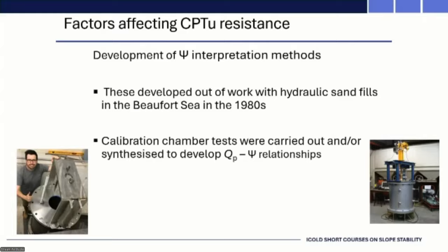The trouble is, we built one at UWA, that's Juan Ayala. Louis referred to the work that Juan did. We built a large chamber and modified it for loose samples, because as you saturate the sample, the volume changes and it starts consolidating. With the old style chambers, you then lose contact with the loading ram because there's too much volume change. With this method, we were able to track that volume change, keep contact, and then apply vertical and horizontal total stress and pore pressure.